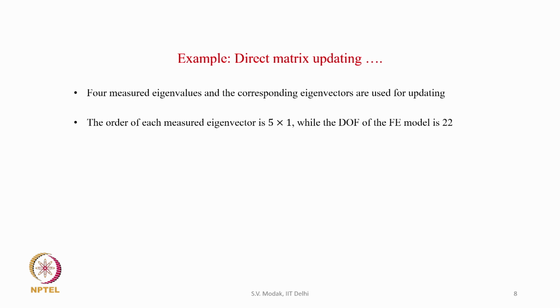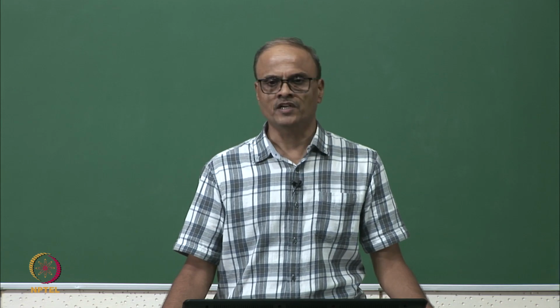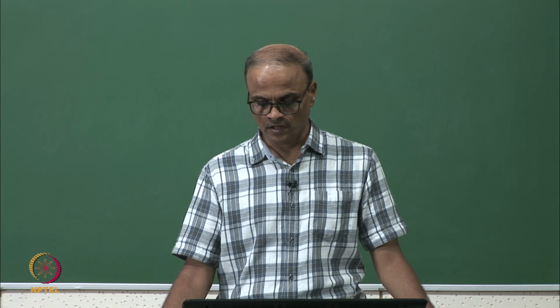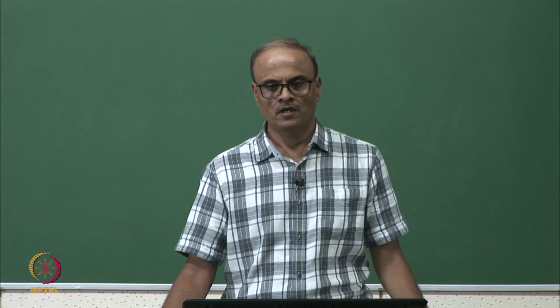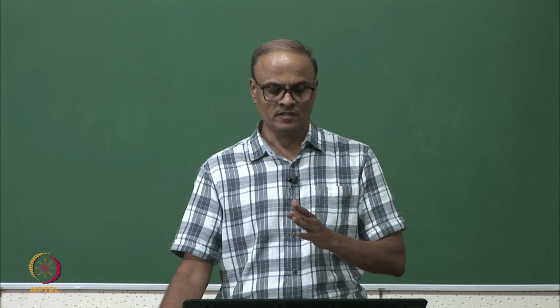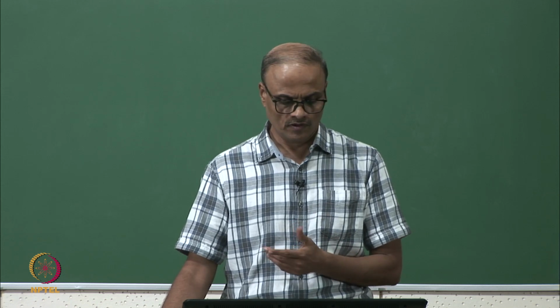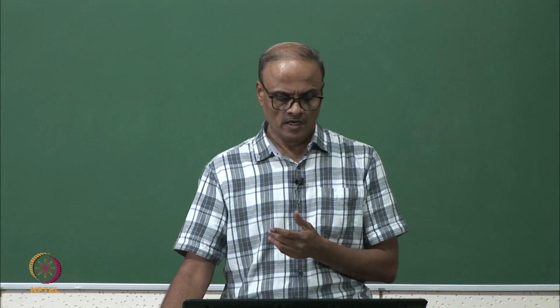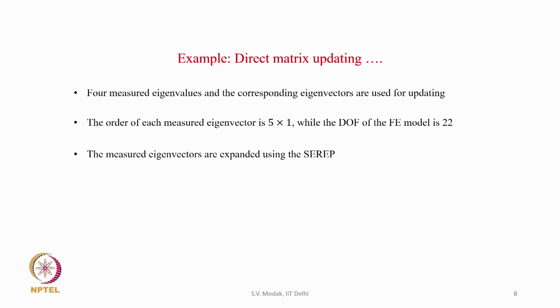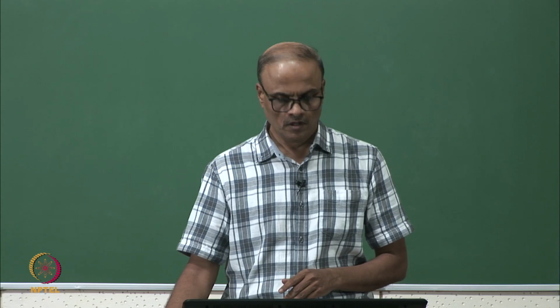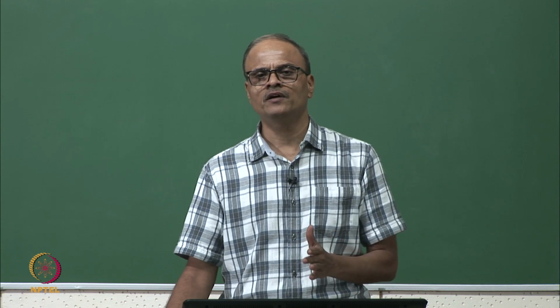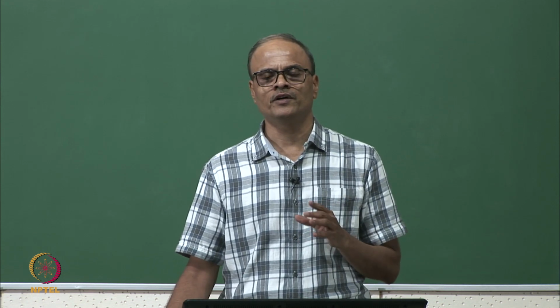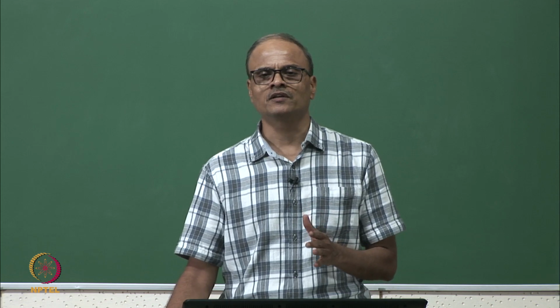So, we see that there is incompatibility between the size of the measured eigenvectors and the size of the FE model. To compute the updated matrices, this incompatibility between the sizes of the eigenvector and the FE model matrices needs to be resolved, and therefore we expand the measured eigenvectors to the size of the FE model using the SEREP method, which we studied in the previous lecture. With these considerations, we now update the FE model and compute the updated mass matrix and updated stiffness matrix.